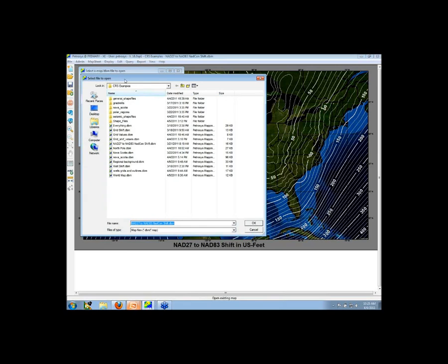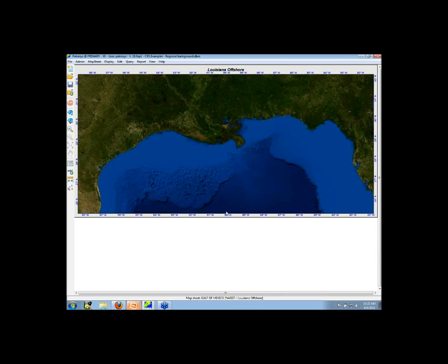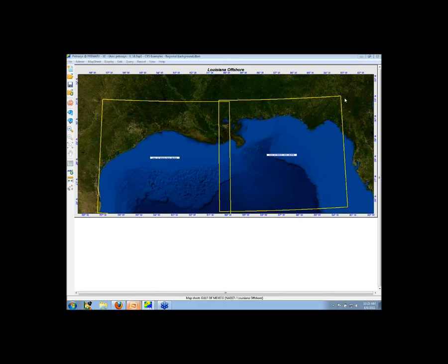All right, so let's zoom back down into our regional map of the Gulf of Mexico and give it a second to pop up that WMS image. And so that was a datum shift. So we're looking at about 105 feet. Now, I'm going to put those outlines again. Now, whenever you're creating new data, like say you're creating surface models, you're creating grids and posting those surface models or those grid files, they need to have some sort of projected CRS to them. So say I'm working over here in the BLM 16 North area, my grids are going to have BLM 16 coordinates, and they're going to show up in the right place.